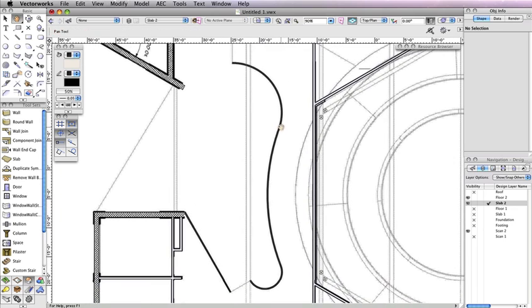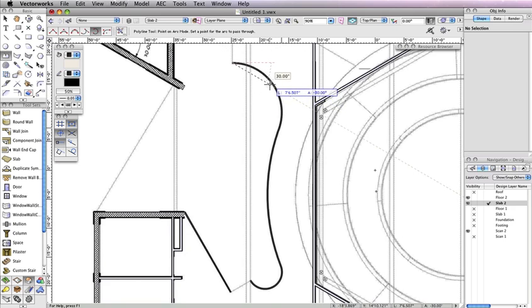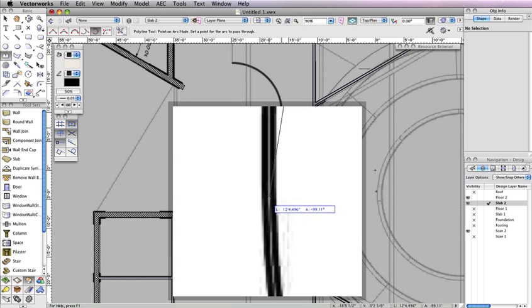To begin, click on the topmost endpoint of this curved shape. Next, click anywhere along the current arc. Then, click somewhere near the endpoint of the current arc, which will also be the start point of the next arc in the shape. Use the scan as a reference for the best place to set this point, based on the curve of the arc.